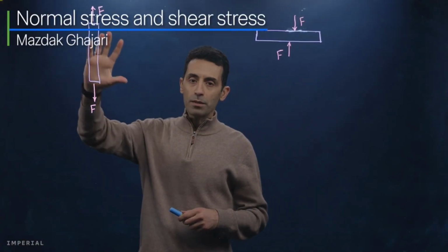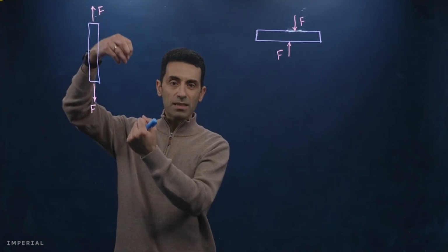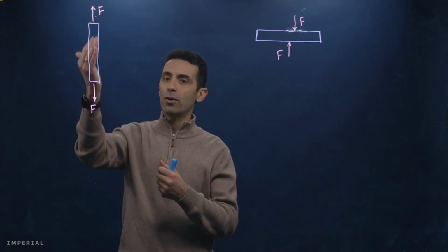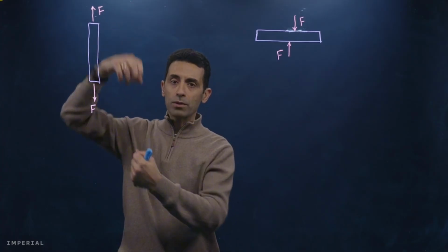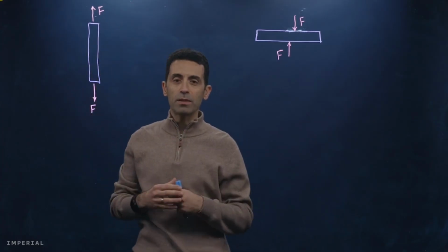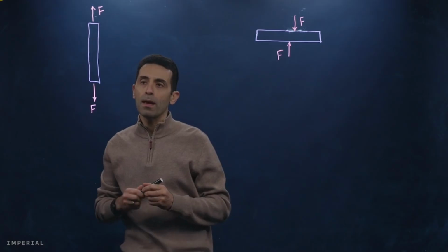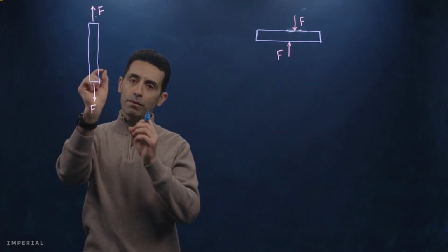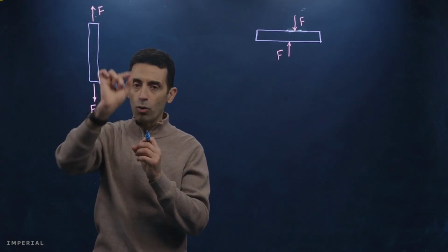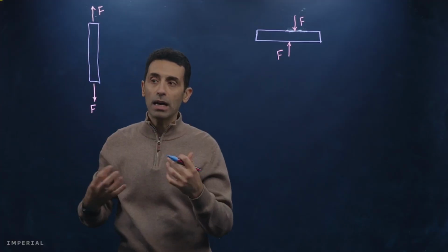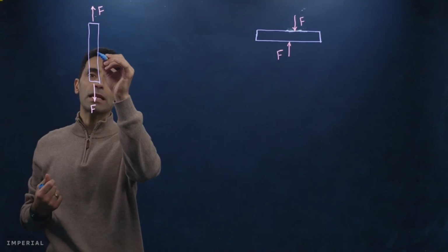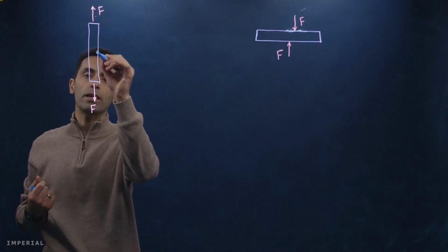So let's look at this bar. This is like a standard tensile test. We are applying a force that is pulling this specimen on opposite sides. You know, this is the type of experiment we do with instrument machines. We can zoom into one point within our domain and extract that infinitesimal element out of it. So if I extract an element, let's say from a region like this,